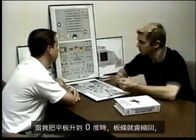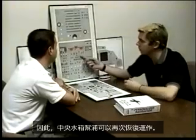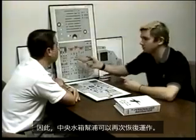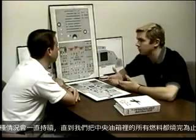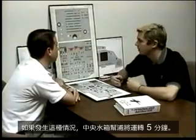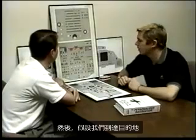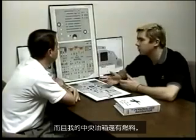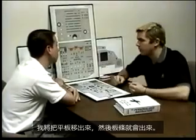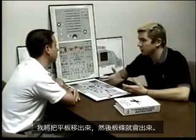I'll take off. When I raise the flap handle to 0, the slats are going to retract, and therefore the center tank pumps can again resume their operation. This will happen until we burn out all the fuel in the center tank. If that happens, the center tank pumps will run for 5 minutes, and then. But let's say we get to my destination and I still have fuel in the center tanks. I'll move the flap handle out of up, and the slats are going to come out.